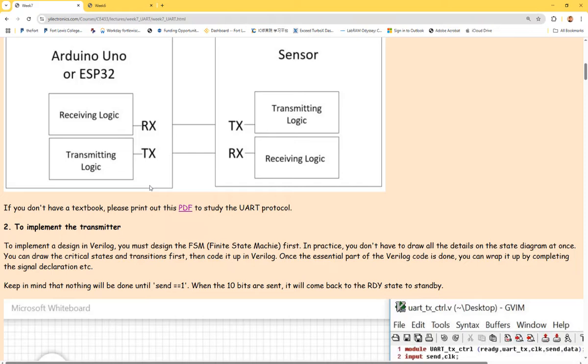And that USB goes to your laptop, and the TX within that USB cable goes to the RX of the desktop or the laptop, which is over here. Whenever you plug in your FPGA to a computer, it already builds a connection. TX, RX, RX, TX is already there. So you're not physically wiring up something, unscrewing all the screws at the back of the laptop and trying to find the pins. No. It's through USB, okay?